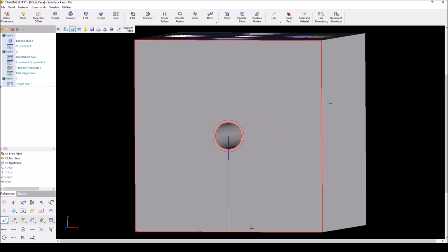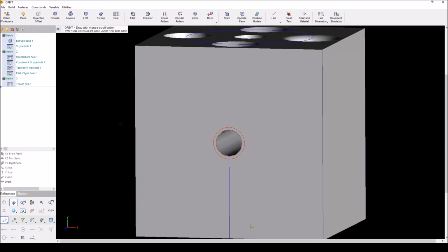And then you will send it to the production floor and they'll be able to read your print and be like, okay, that calls for 1/4 by 20 hole, and then you get myself a 1/4 by 20 tap to create this hole with, so on and so forth. So that's the hole tool.